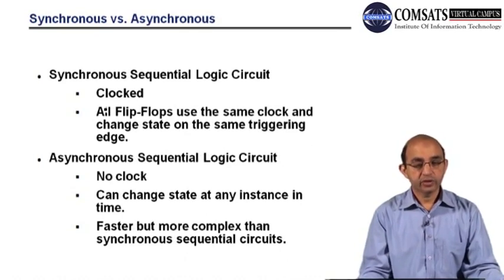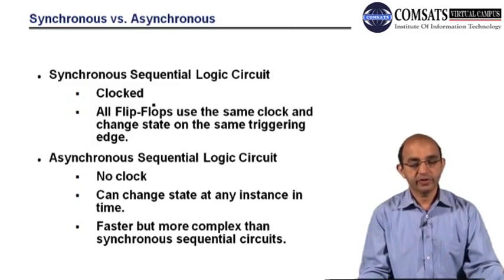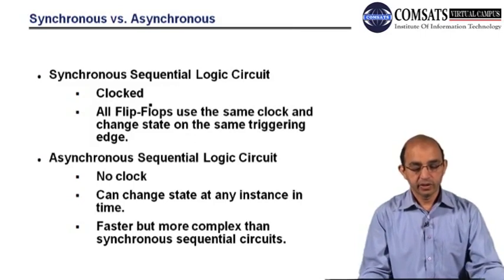Then we talked about synchronous and asynchronous. In synchronous sequential logic, all the elements are clocked. On the arrival of the active clock, all the sequential circuitry will function. For example, we have flip-flops that are using the same clock, so it means we have a synchronous sequential logic implementation.